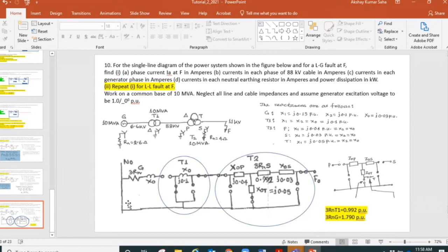You used it in Power Systems 1, and we used it in this tutorial session last week. What is the formula that you use for converting an ohmic value to per unit? It's actual over base. Actual ohm by base ohm. But if we don't have the base ohm, we can do it directly.